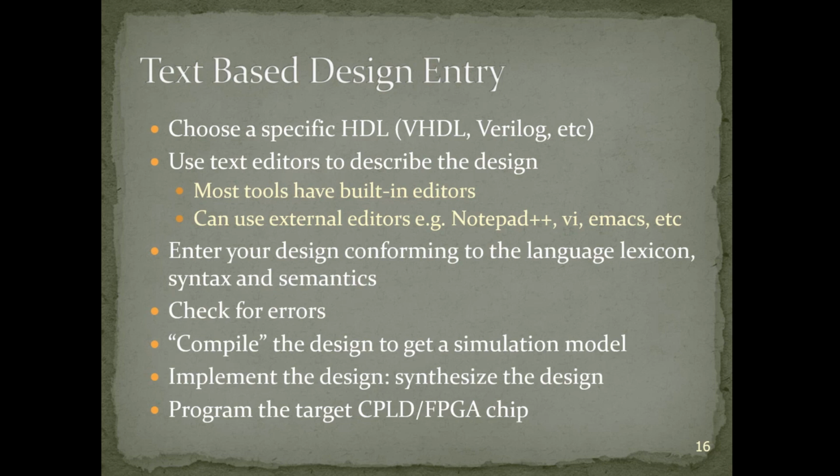It's not going to tell us that it works correctly or not. It's our job basically to look at those output waveforms and see if they work properly and they match what we would expect for those kind of inputs. If that's fine, then we proceed to the final step, which would be to synthesize the design.